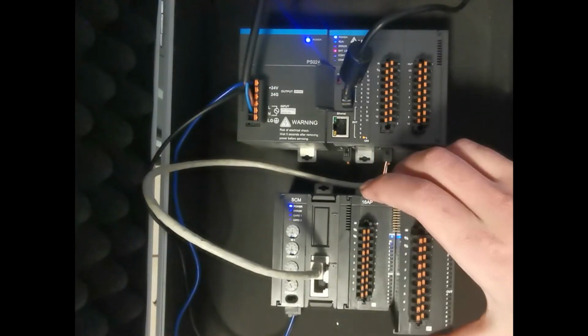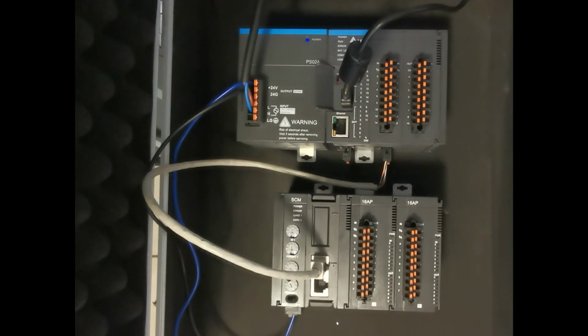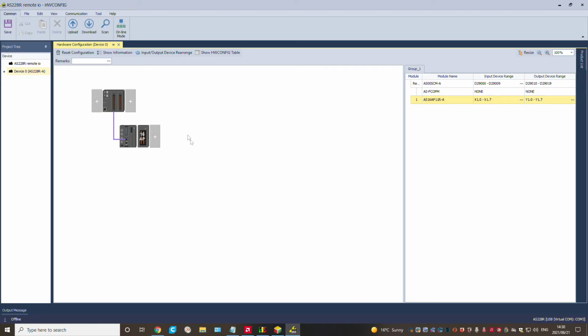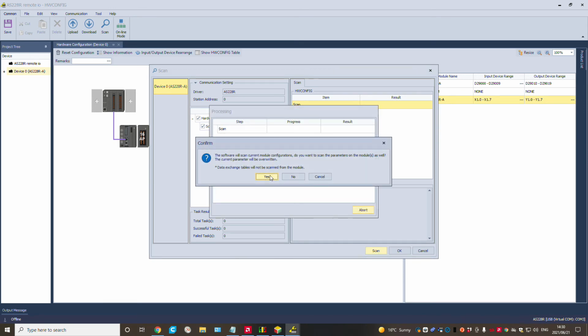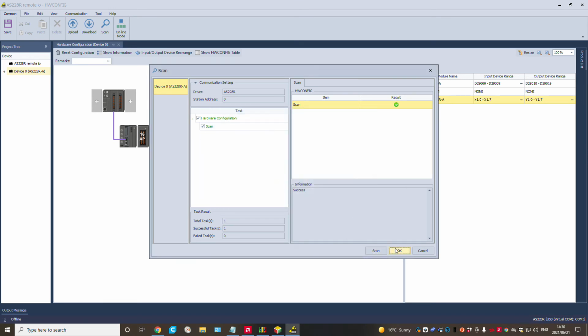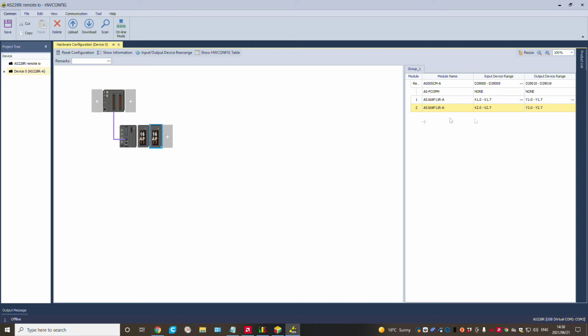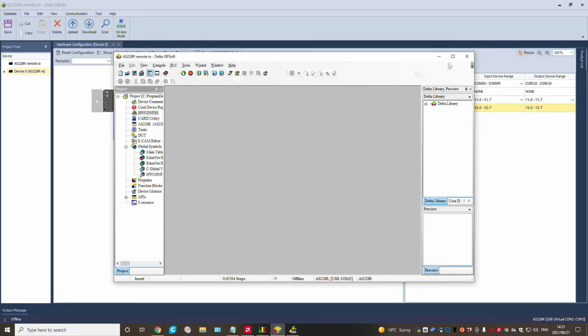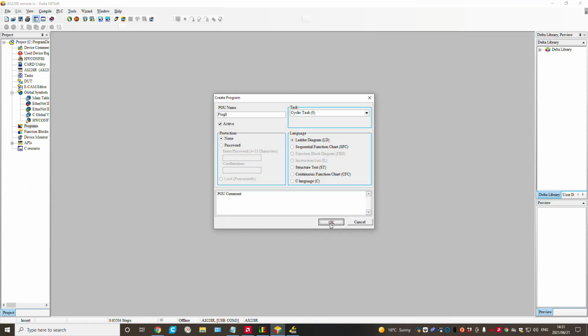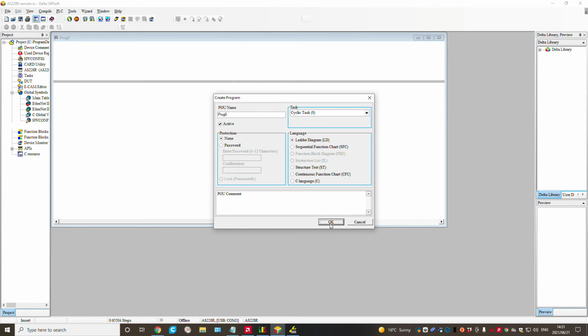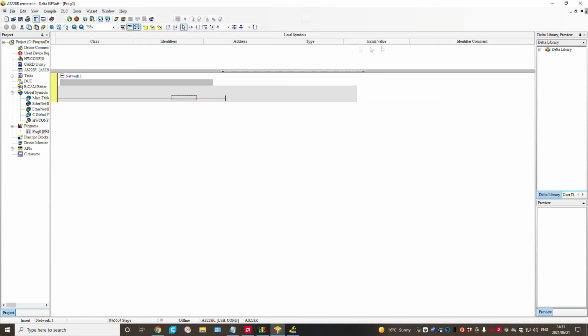If we want to add a module, we can simply plug it in, power cycle the remote module and PLC, do a system scan and download the configuration to the PLC. To display the correct operation of the RTU module, we will write our correct output number using the system memory SM407, which is a 1-second internal pulse for the PLC.